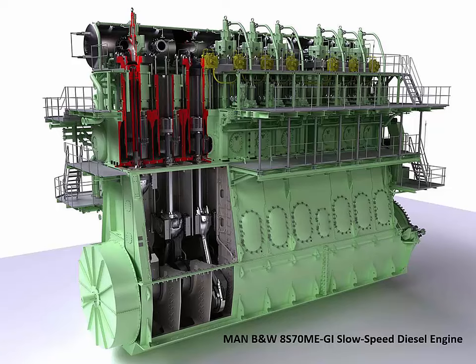To allow for a reduction in the size of the receivers, typical storage pressure is between 25 and 30 bar. 30 bar is around 450 psi. This is high pressure air. So high pressure air receivers hold an enormous amount of energy, and extreme caution should be exercised when working on these systems. You don't work on these systems until they're drained of pressure. It is extremely dangerous to work on any fittings, valves, or components of the start air system if there is any chance that they are pressurized.